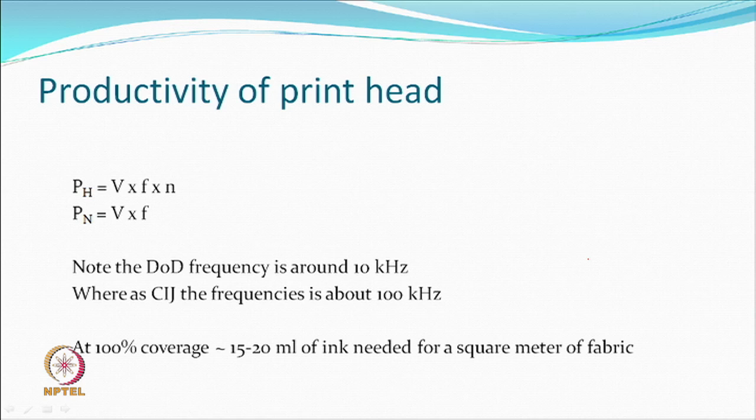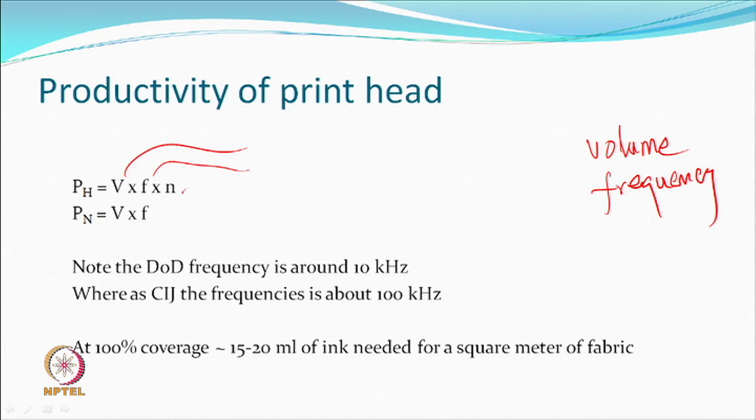So, productivity of a print head, let us say print head productivity pH, is the volume of the drop, the frequency, and the number of nozzles.